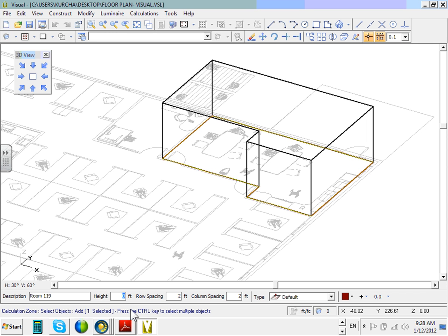Or 2.5. Why 2.5? Because if you look at the desk, guys, the desk height is almost 2.5. So they want us to give the best lighting system at 2.5 so people can perform their job professionally and fast and efficient, right? We care less about the floor. Very few of us lay on their tummies and do their work.